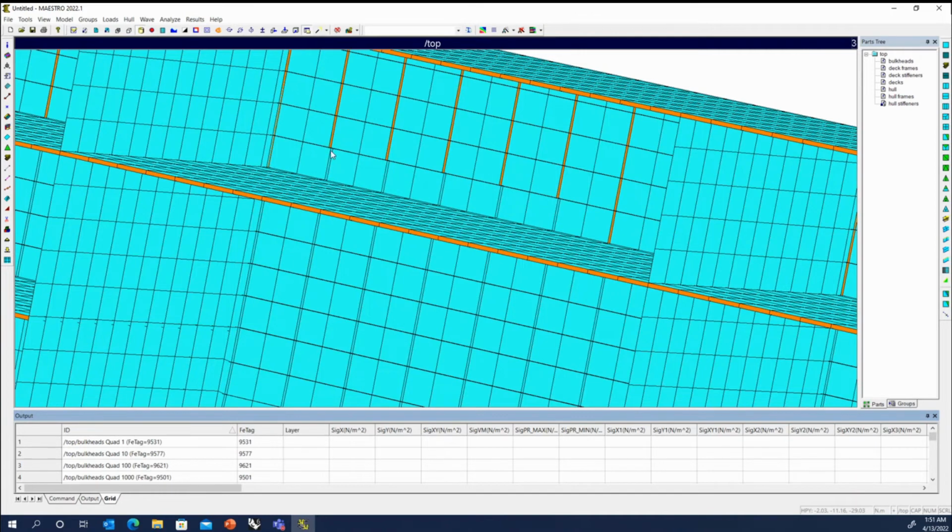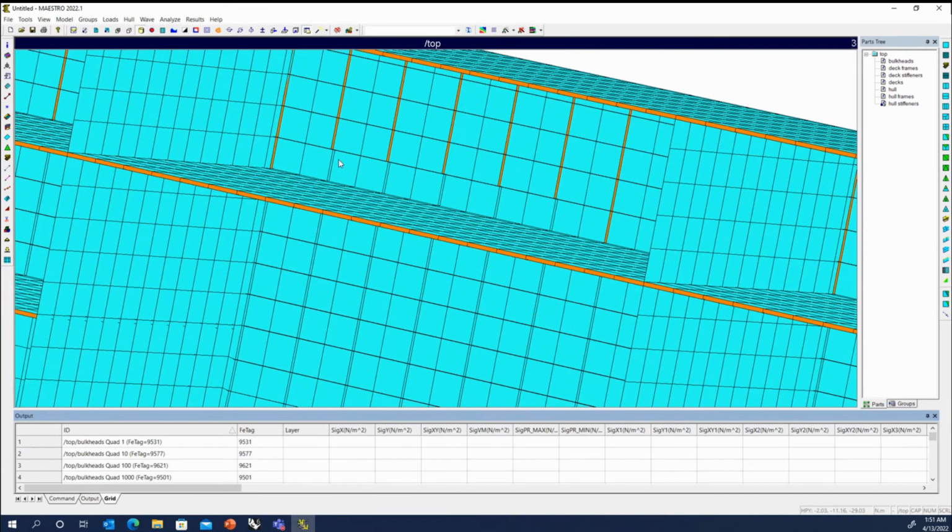When it went to look at this beam segment and find the corresponding node, I had given it both of these meshes as reference meshes, and apparently when it searched, it found the node from the lower hull mesh with its outward normal, and that's what it used to assign that beam segment. When it searched the next segment, it looked for this node, and that was only on this upper mesh, which was pointed inward. So it used that normal. But that's why you see some of these flip-flopped.